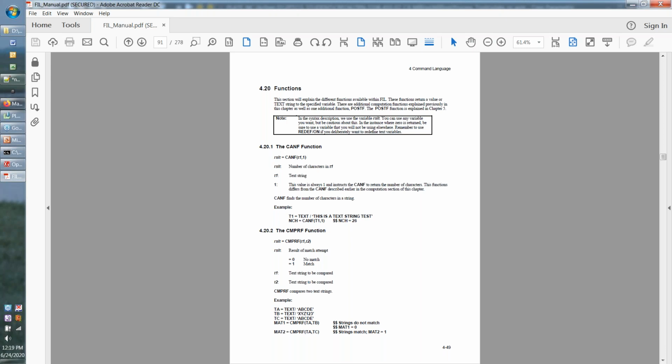The language is powerful because it enables you to do anything you want in line with an active post processor. I tell everybody that's kind of like Swiss Army knife stuff, right? You can save yourself with it and cut your fingers off all at the same time. So note that FIL works a little bit like that. These things should be approached with a tedious, scientific method, for lack of a better description, in terms of both creation, troubleshooting, and management of a post processor. Your very expensive machine tool on the floor is hinged on that. Clearly, bad things in a post can cause enormously expensive results on the shop floor. So be aware of that.